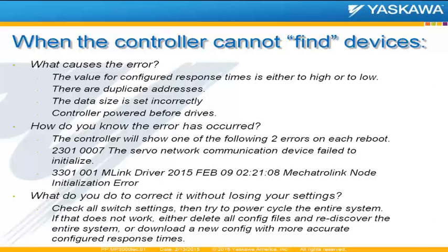How do you know this error has occurred? You'll see one of these following two errors on each reboot: the servo network communication device failed to initialize, or Mechatrolink node initialization error.